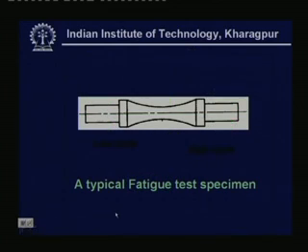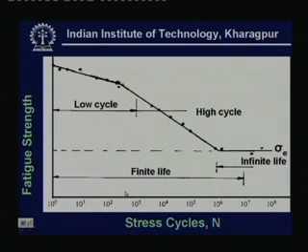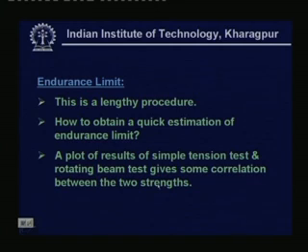Now, what you get after such data is plotted onto this type of schematic diagram, I have just shown you a schematic diagram. You see the ordinate has the fatigue strength and the abscissa is the stress cycles, as I just explained earlier. Now, you can see the more the load or the fatigue stress onto this material, the lesser the number of cycles it can withstand.